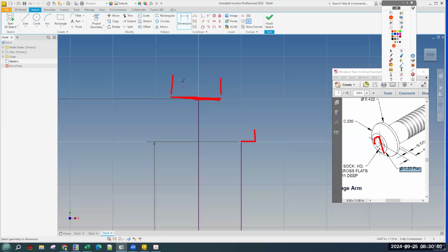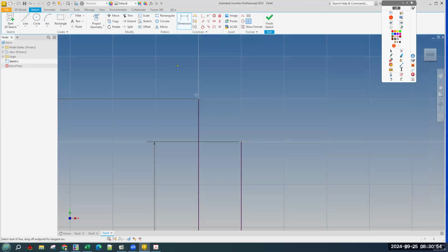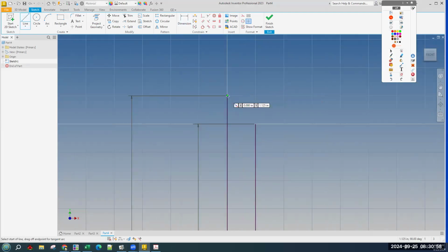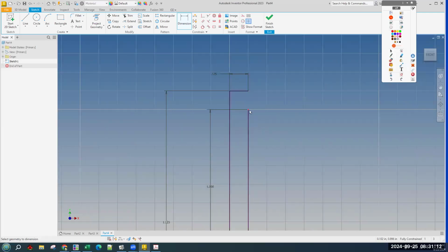We know that the flat surface needs to be 0.25 across, which means the short line that we need to draw attached to the top is half of 0.25. So let's get a line, and from the top of our tallest point, go horizontally, and we want it to be 0.25 across. So this is a half of that, 0.25/2. Okay, and so that sticks it out that way.